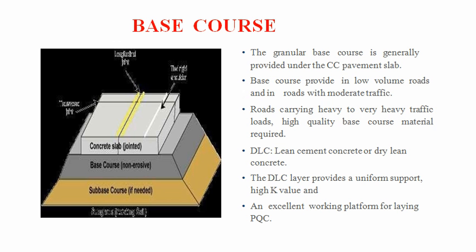Next is the base course. Now the granular base course is generally provided under the cement concrete pavement slabs in low volume roads and in roads with moderate traffic. For roads carrying heavy to very heavy traffic loads, high quality base course materials are required, and lean cement concrete or dry lean concrete is used.